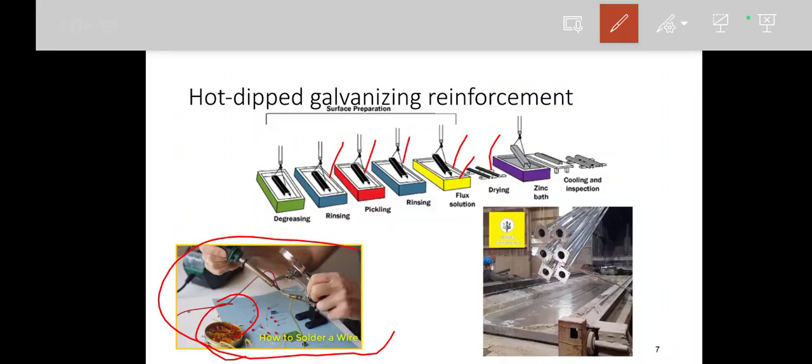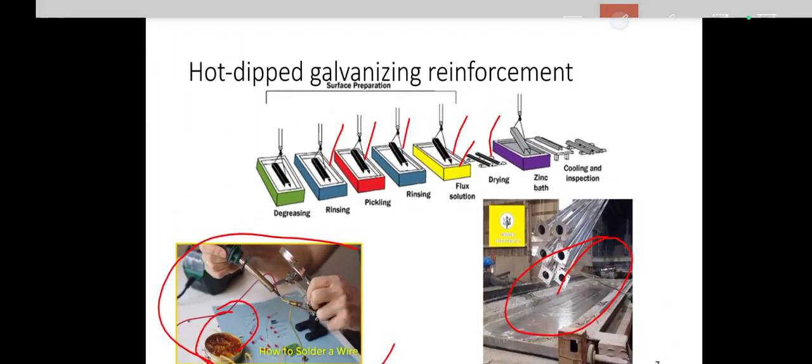After drying it, we have to dip it in molten zinc, so that it will have a uniform coating of zinc. So only it is called hot dip galvanizing. Here we can get 99.9 percent pore-free coating, so thereby the process of corrosion can be reduced.